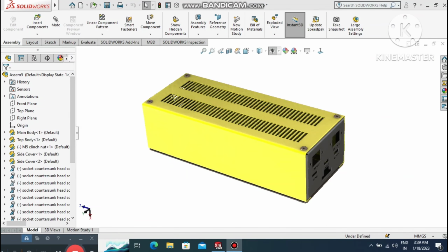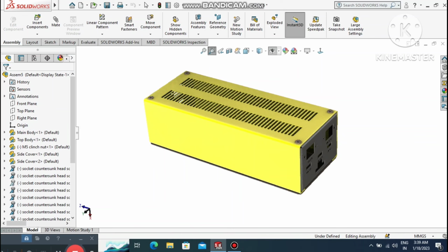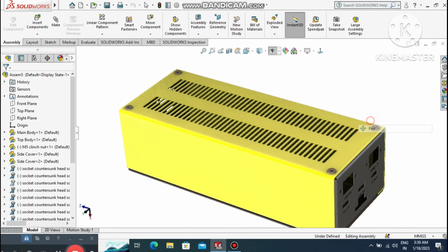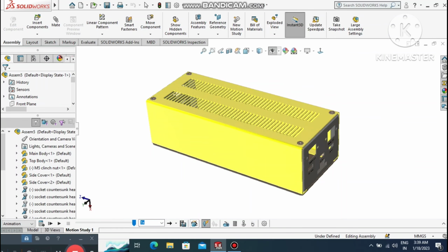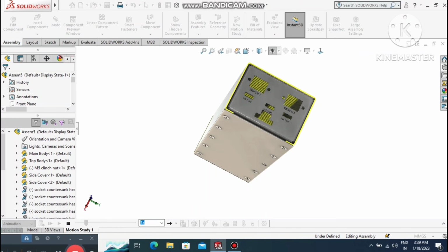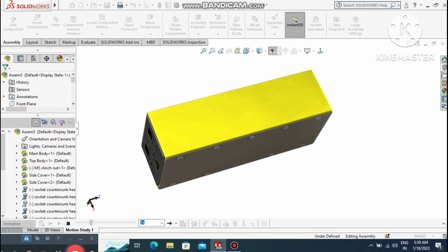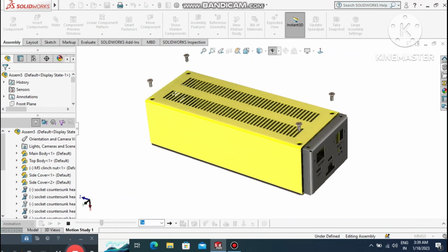So look how, and here we create the animation for this electrical enclosure. So look how we create the animation and create all this part in sheet metal, and we apply various sheet metal parameters like bend radius, edge flange, flatten pattern, and later we give the DXF file for cutting purpose. So look how industry uses sheet metal fabrication works to their design. So look how we do this, and it is better for beginners and advanced level SolidWorks users.